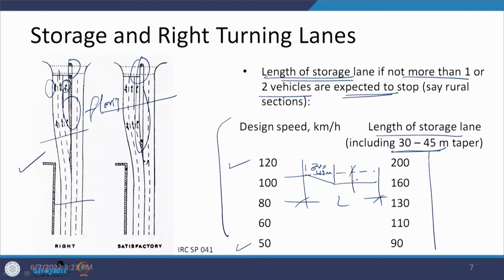Now, let us assume that we have this particular lane which is being utilized for right turning. If this lane is 3 meters wide at a minimum, then this flared section is going to have 1 in 10 to 1 in 15 as a rate of taper. That is going to be the minimum value, as 1 in 10 is usually considered one of the minimum values here.